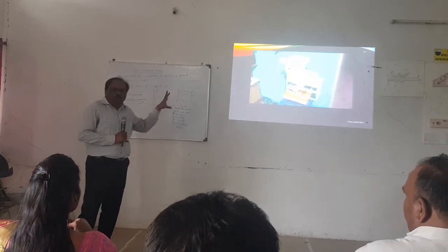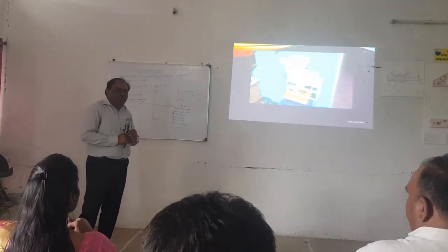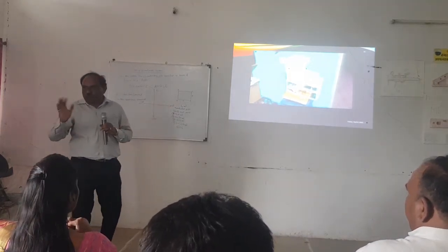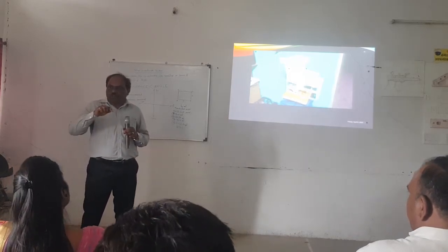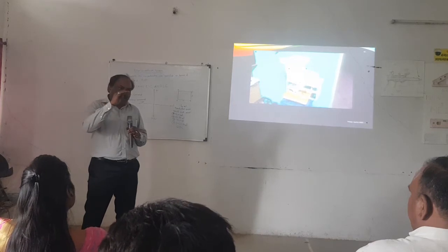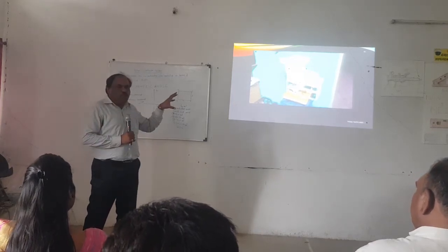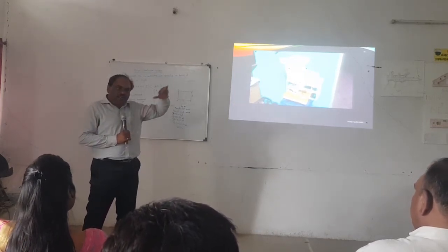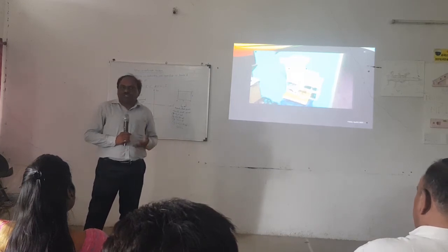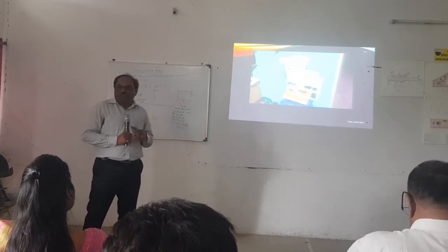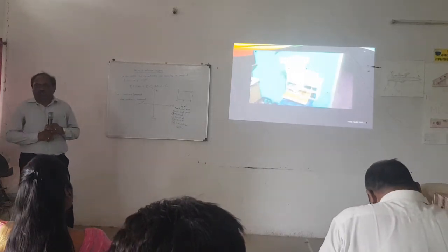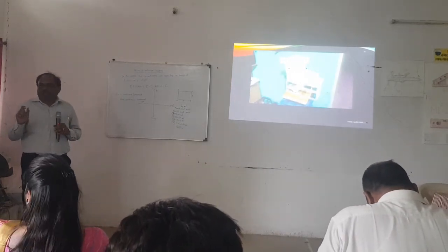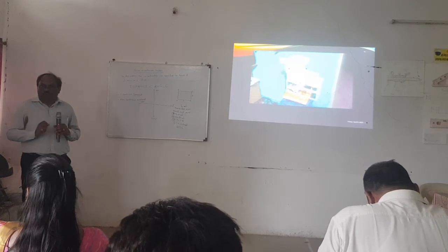There is a lot of scope in actually RP research. So these models are not so smooth. There is actually a staircase structure because they are printed layer by layer. So some research is going on for removing the staircase structure. Some research is going on for increasing the speed of the RP machine. Then increasing the fineness or coarseness of the machine.